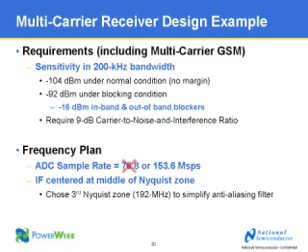Okay, now remember, we're designing this thing, and we want to be able to measure how good it is, so we're talking about the sensitivity. In this case, we're going to design the system so it can handle multi-carrier GSM signals. The reason is that multi-carrier GSM is the most difficult spec to meet. So if you can meet multi-carrier GSM, then you can meet WCDMA, you can meet LTE. It's the most difficult, so that's what we're shooting for.